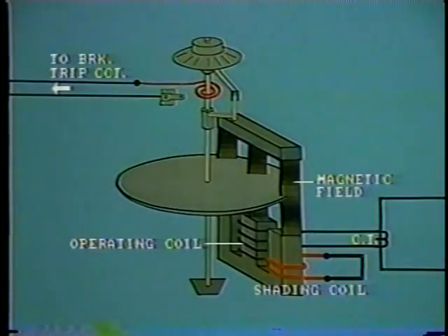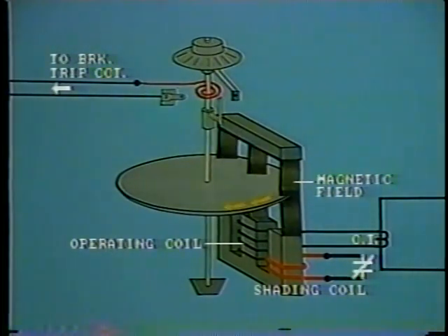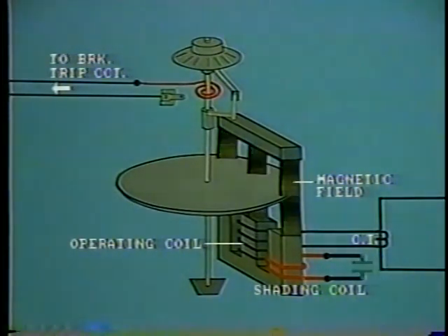You will remember that the time overcurrent relay is fitted with a shorted shading coil on one leg of the electromagnet. This is to provide the driving force. The shorting circuit is fitted with a contact, which is operated by the directional element. When current flow is in the tripping direction, this contact remains closed and the overcurrent relay can operate. However, if current flow reverses, then the directional element opens the contact, so preventing operation of the time overcurrent relay.